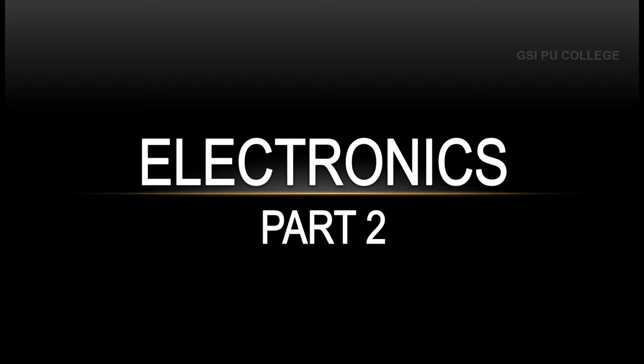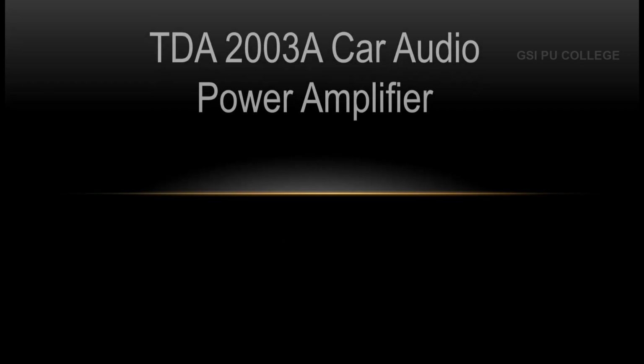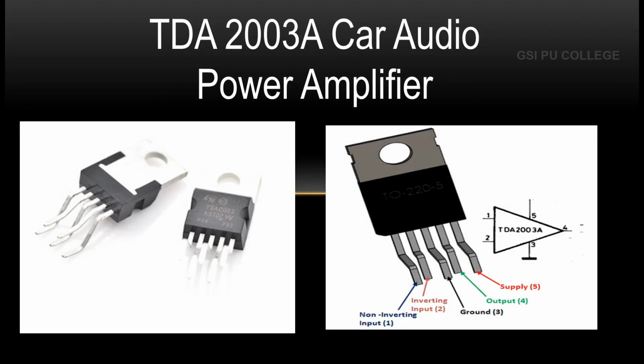In this session we are going to see the other packages of op-amp, that is TDA 2003A car audio power amplifiers. Even the car must have some amplifiers, and the amplifiers present in the car are TDA 2003A car audio power amplifiers. This TDA 2003A is from ST Microelectronics, a high performance audio amplifier designed only for car radios. This 10 watt amplifier will deliver an output current of 3.5 amps and uses a power supply of up to 18 volts DC. The 5-pin pentawatt package offers savings in space and cost, requiring only a few external components.